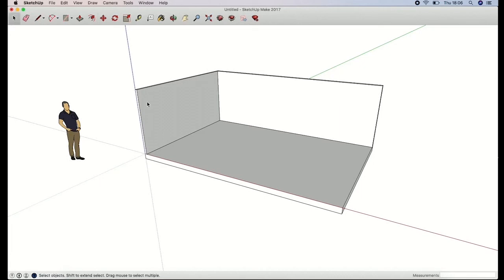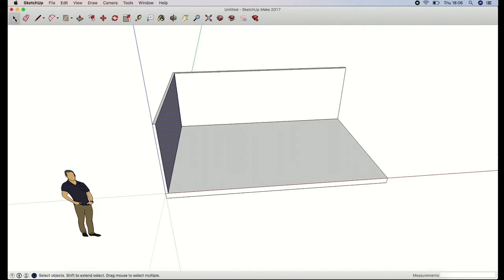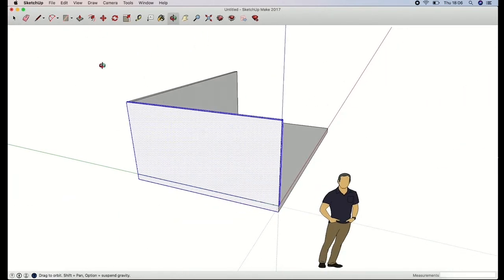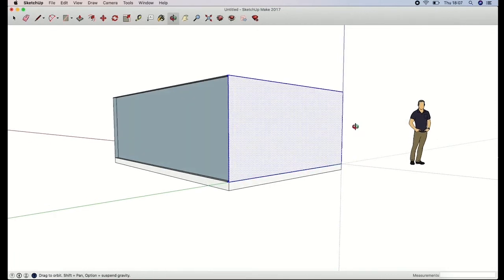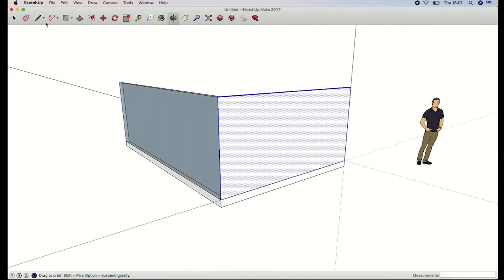If I want to copy and paste this wall, I can select the surface, but maybe if I go this way, using the arrow and then selecting this wall, and maybe deselecting. If you press shift, I can deselect that tiny bit at the bottom and also see the other parts I've selected. So if you hold shift down while you're on select, you can deselect certain areas and also surfaces. So yeah, that looks fine. I'm just going to deselect this tiny bit here as well.